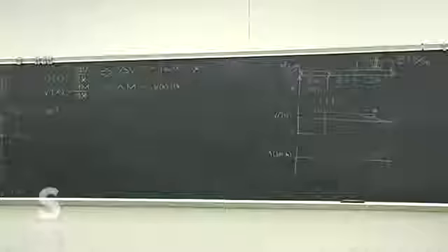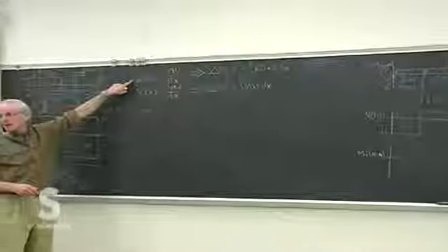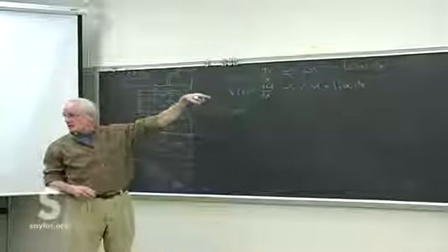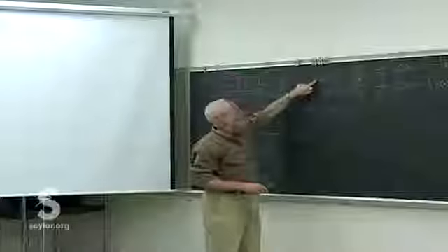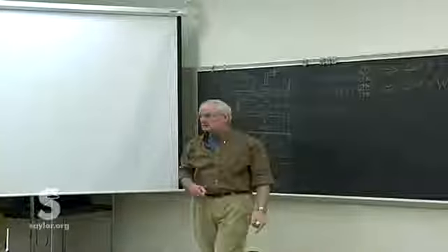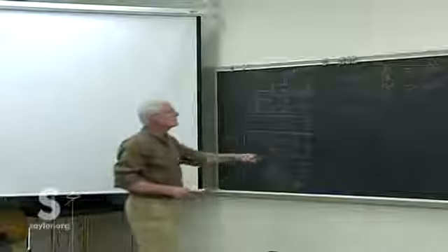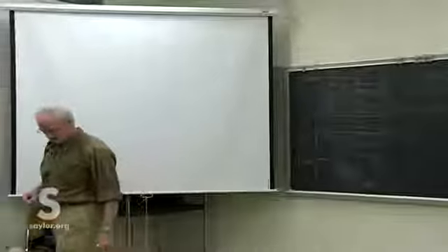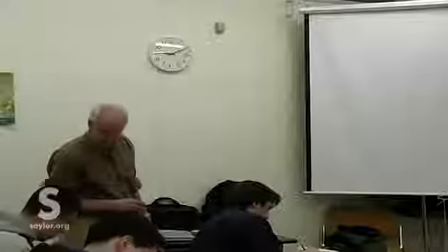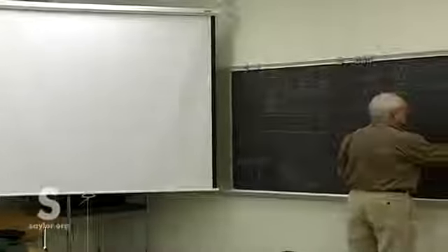Because of this right here, in our relation, a distributed load down is considered a positive load. So we put a negative on it, and then the slopes match. That's the only one of those relationships that has a negative sign in it. Well, I guess the equivalent one of delta V does. And that would all match with our convention of positive directions.